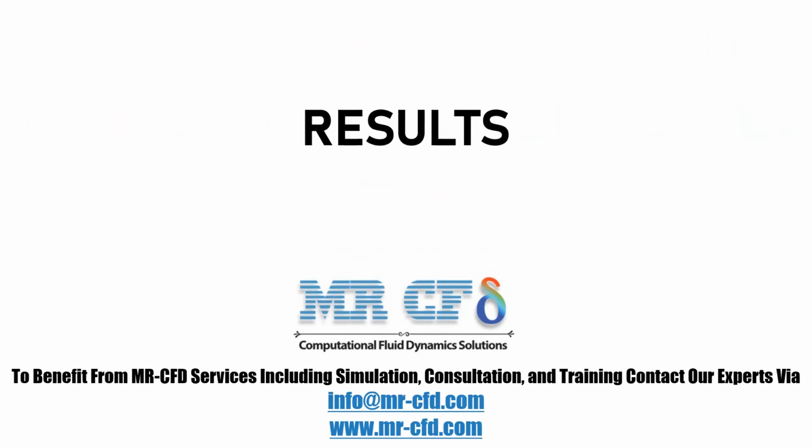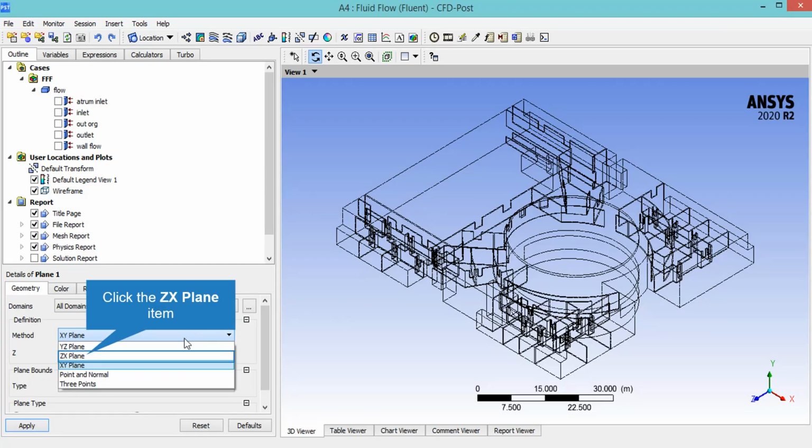Contours of pressure, velocity, velocity vectors, and streamlines are presented to you using CFD-Post software. After clicking on Location and then selecting Plane, a new window will appear. In the appeared window, under the Definition section, in front of Method, we click on ZX Plane and then set the value of Y to the defined value. And then we apply to create a new plane.